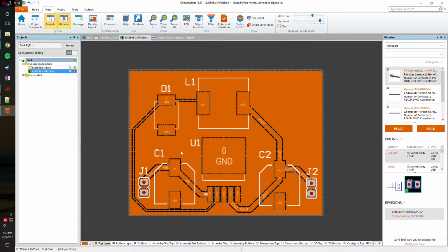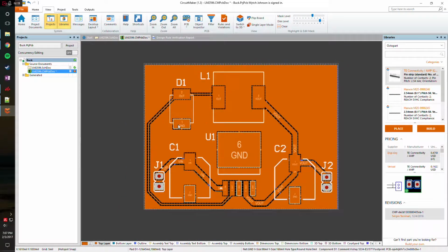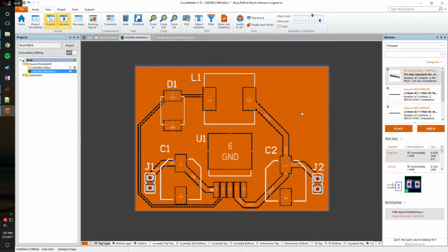That's all done. And in this video, I'm going to explain now how, if I want to take this PCB, I can export it in a particular format so that I can have it manufactured at OSH Park, or maybe I want it to be milled if you have a mill at your school or whatever. How can I do that? You do that by exporting it to what's called a Gerber file.